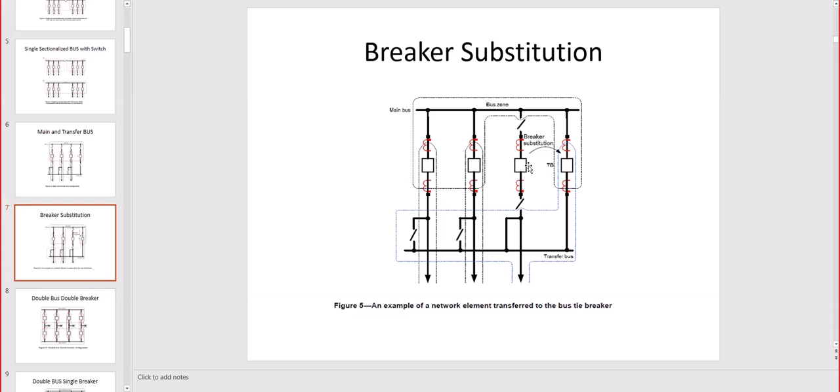And then we're going to open the breaker, and last we will open the switches upstream and downstream of the breaker. So always the switches are after the breaker when we disconnect, or if we connect a breaker with switches, the switches are before the breaker. The switches cannot handle the inrush currents and the mechanical stress as a breaker does.